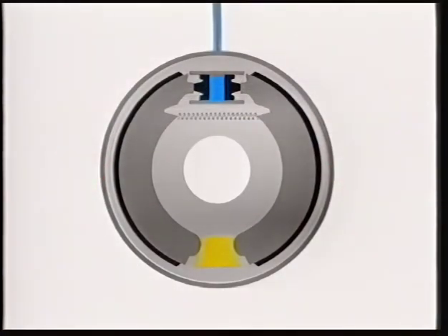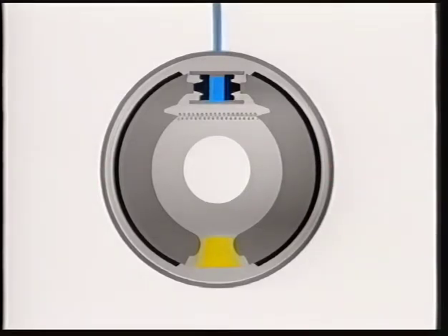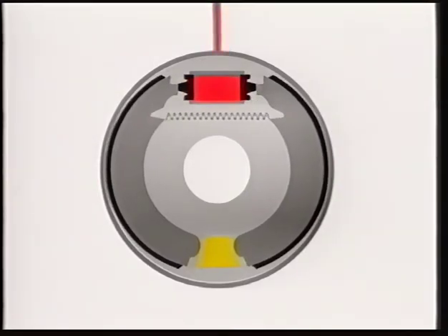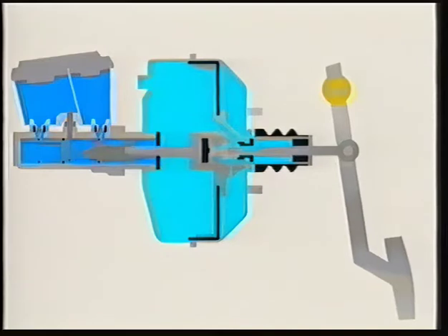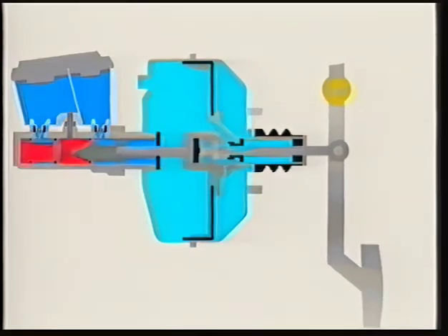Low pedal problems with these types of brakes are caused by excessive clearance between the shoes and drums. This in turn causes the wheel cylinder to move further than it normally would, requiring more fluid from the master cylinder and resulting in longer pedal travel.